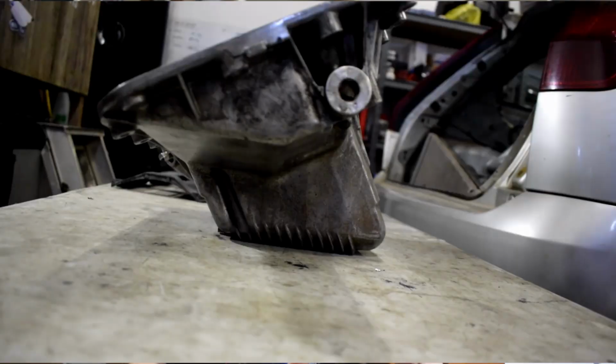So we're dealing with this problem, but also the oil is in a very, very small area and the sump is angled. So when you apply this kind of load to it, it just simply sloshes out of the way. Now why would it do that when we have a baffle already in place? We've baffled it, we have the windage tray, we've got this ring at the bottom, we've done a lot to try and limit the surge.